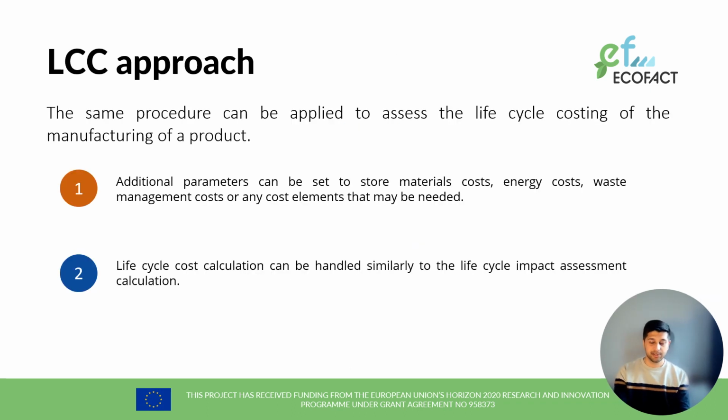Now let's apply the same procedure to evaluate the life cycle costing of manufacturing a new product. We have the flexibility to set additional parameters in SimaPro, capturing material costs, energy expenses, waste management costs, or any other relevant cost elements. Now, calculating the life cycle cost mirrors the approach that we took for life cycle impact assessment. It's a similar journey, ensuring a comprehensive understanding of both the financial and environmental impact of a product's life cycle.